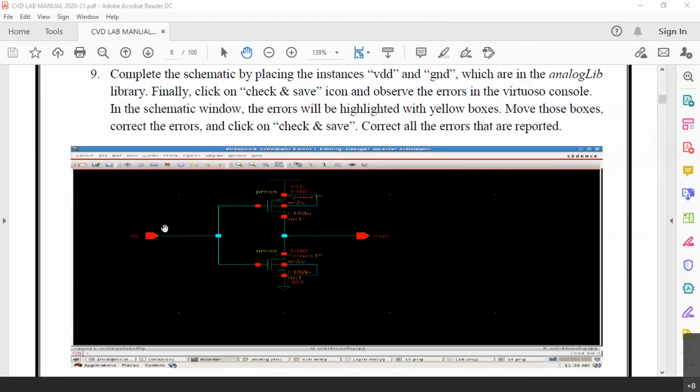This first one is the circuit diagram, which we will directly convert into layout. If at all we put the power supply and input pulses here itself, then in the layout, they will not have any counterparts. So it is better that we create one symbol and using the symbol, we perform the simulation. Otherwise also creating symbol is a good method.